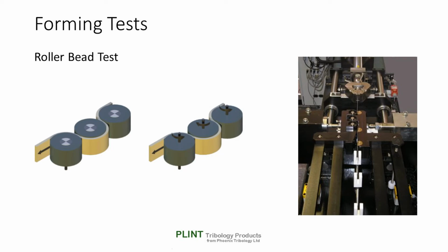The clamping force set point established in this way should then be verified with a trial test, during which the behaviour of the tool is observed. If the tool remains shut when reacting the force normal to the sample, in the direction of the clamping force, then an adequate clamping force set point has been applied. If the tool opens, the test is repeated with a progressively increasing clamping force until the tool remains shut.